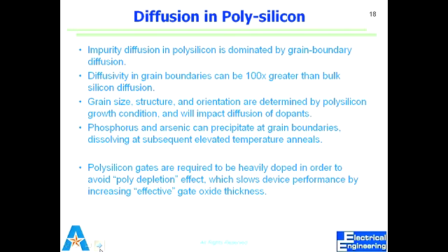So grain size, structure, orientation is what we defined during our poly deposition. Right? Poly is deposited by LPCVD, and we'll see LPCVD later on. But that can cause a problem: if you have heavily doped poly, then again our temperature budget reduces. We cannot elevate the devices to high temperature, because the dopants can subsequently dissolve and get into the substrate.